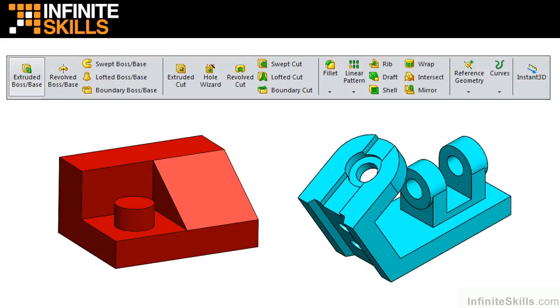The next major area we will cover is part creation through the use of 3D features. After the sketch is completed, we then utilize the appropriate feature to give us the desired results. Features are the building blocks of the part. They are the shapes and operations that construct the part. Features typically begin with a 2D or 3D sketch of shapes such as bosses, holes, and slots. This shape is then extruded or cut to add or remove material from the part.